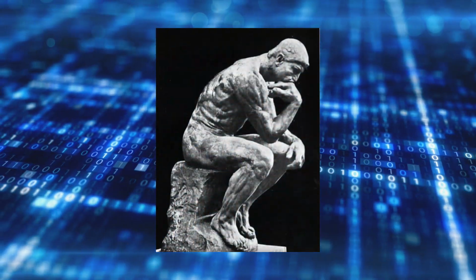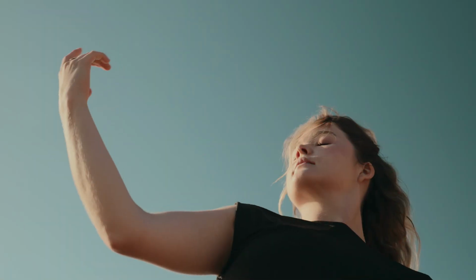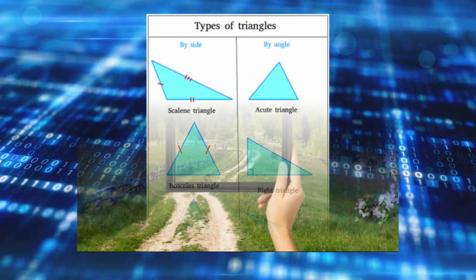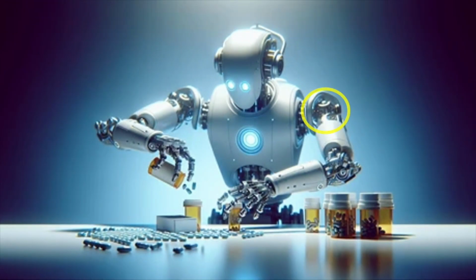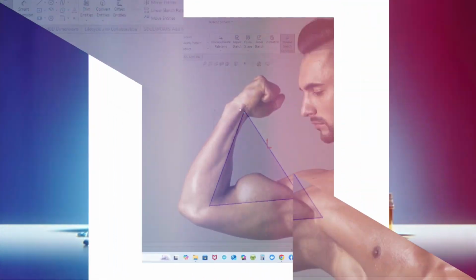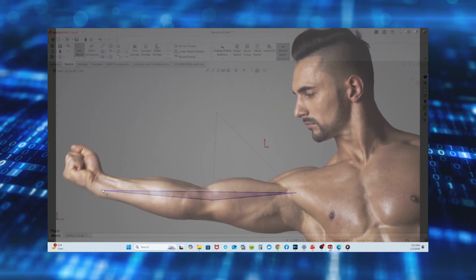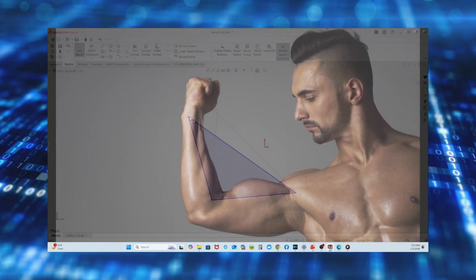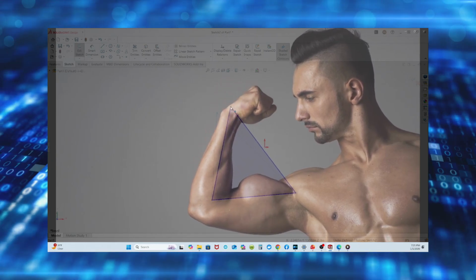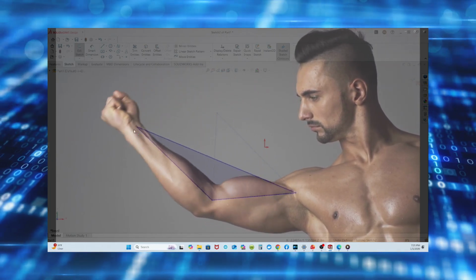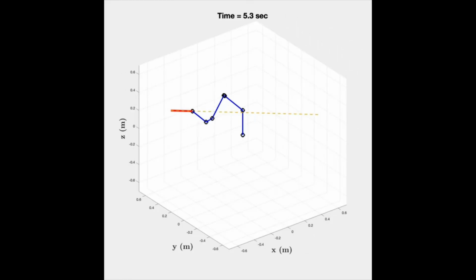Now here's an interesting thing to think about. The movement of the arm can be described by simple geometry. Picture for a moment that there is a point in the center of your shoulder, in the center of your elbow, and the center of your hand. You'll find that no matter how you move the arm, those 3 points create a triangle. Knowing where the starting point, center point, and end point are, along with the distances between, are all the information we need to calculate the joint angles of the arm at a specific endpoint position.